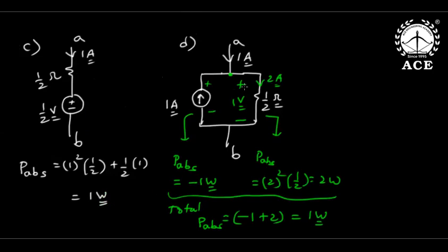But after substituting like this, if you observe, this became a source. Power absorbed is negative, and this became a sink. Power absorbed is positive. But overall power absorbed is positive, which means overall this branch is again a sink absorbing the same power. Overall this total system is a sink absorbing the same power. So we did not violate the law of conservation of energy. Now you can show any combination, sir. Yes, you can show any combination.